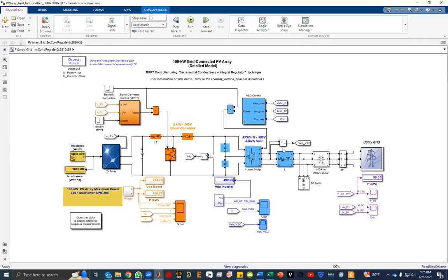So we are going to get approximately 500 volts on the DC side. We'll get somewhere around 250 to 260 volts on the AC side. Since it is getting 500 volts, because there are some losses, and also this 500 volts is split into two to make an AC, so it will be approximately two, not exactly.